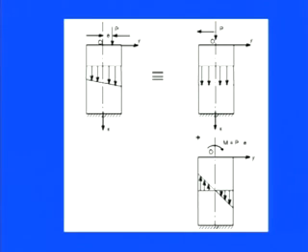So we have two main components. If an eccentric load is there, one is the axial load, that is P, which we are considering and assuming that it is now on the centroid part, and second, due to eccentricity, we have this bending moment which has the magnitude P into e. Now this bending moment will tend to move this object in a clockwise direction. And then you can see the nature of the tendency.